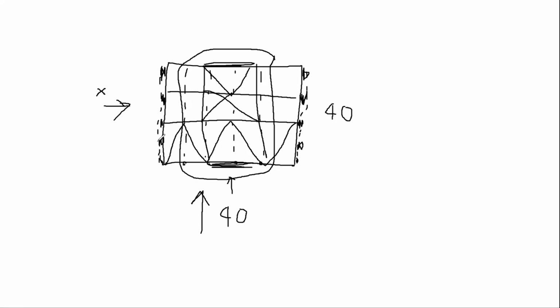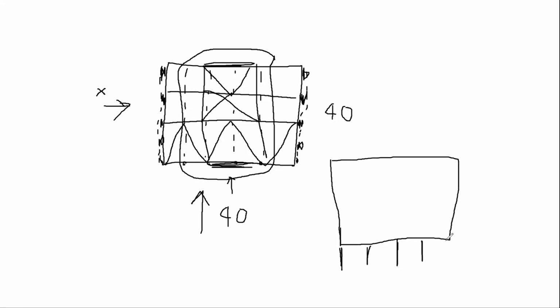But there are many alternatives to doing this. Like if you wanted to, you could have the same wide span structure and you could resist the earthquake loads with, say, 4 or 5 shear walls in plan like that. And so that would mean that you wouldn't have any moment frames or shear walls, excuse me, on the sides of your building here.